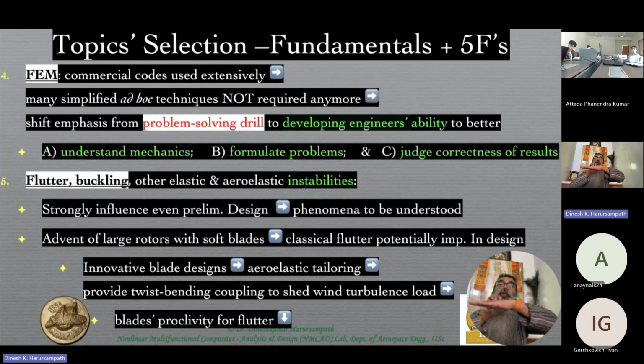But essentially, we are doing away with hinges, we are doing away with bearings, and we have what are known as hingeless, bearingless rotors for almost a decade or two now. In fact, when you're working on the assignment for ALH or LUH, you will see, at least for the tail rotor blades, for example, a hingeless, bearingless kind of configuration. So in such situations, you are having fairly soft blades, especially where the tapering to the thin section is there. You would have a softer blade. In other words, it's much more flexible.